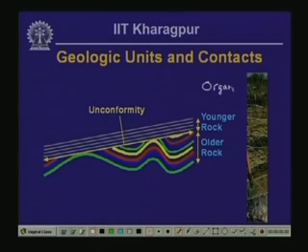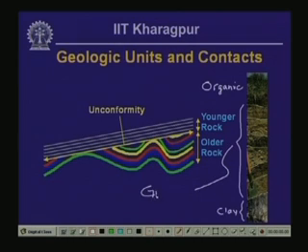So, this is the layer in which you have got some organics. The roots of the overlying vegetation actually penetrate this layer, and there is activity of different types of organisms. Then underneath that layer is a sequence of primarily granular soils of brown color, which extends up to the bottom where the shovel is kept. So, this is the layer of basically sands, silts and gravels. Underneath that sand, silt and gravel sequence is a layer of clay of gray color. So, this is the clay unit, and this one here is the unit that comprises granular soils.